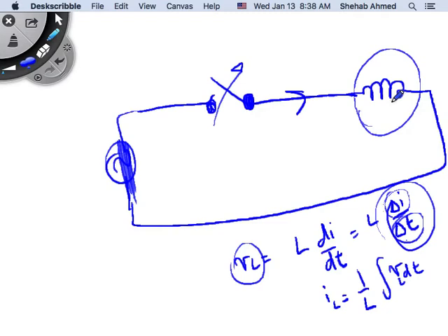And that's the difference between the different types of circuit breakers. Different types of circuit breakers quench this arc in a different way. Some are air circuit breakers. Some are vacuum circuit breakers. Vacuum is probably better than air. A vacuum does not allow the burning process to continue and tries to quench that. Air circuit breakers are the cheapest, but they're the biggest for the same voltage level. Vacuum circuit breakers are a little bit better. Oil circuit breakers, maybe a little bit better. Gas insulated circuit breakers use a very good gas called SF6 gas. Gas insulated circuit breakers are the gold standard, but they're very expensive.